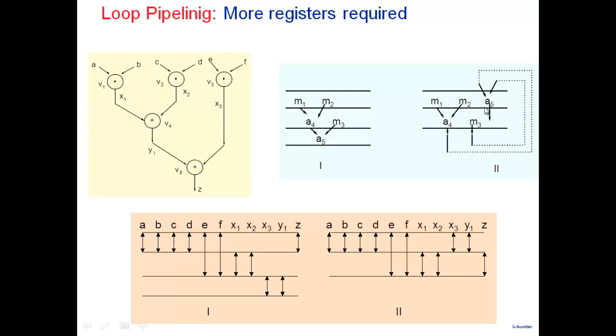In terms of how do I schedule my operations here, can I pipeline my system and do operations simultaneously? Okay. So we have seen as soon as possible scheduling, as late as possible scheduling, to give us an idea of the freedom that is available. Looking at chaining of operations within the same clock cycle, multi-cycling, taking an operation and allocating more than one clock cycle to carry it out, and loop pipelining, pipelining a loop in order to carry out the process here.